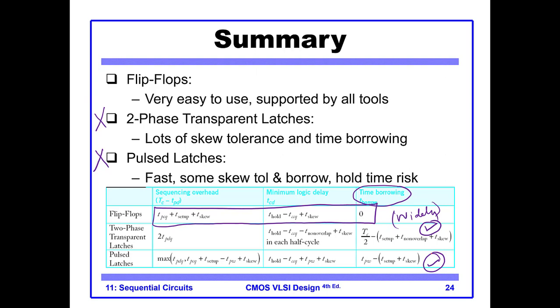So we discussed the design of the D-latch, and we discussed several designs based on feedback, based on non-feedback, based on mux, based on inverters. We designed flip-flops from inverters and from mux. We added several signals like set, reset, and all those things. And most importantly, we discussed the timings. So all the details about setup time, hold time, and how to find the maximum frequency, and how to ensure that the chip is working. In order to ensure that the chip is working, the hold time constraint is very important. Okay, with this I finish this part of the lecture.